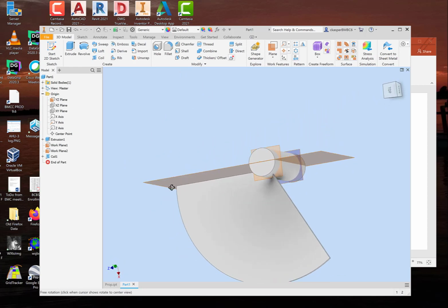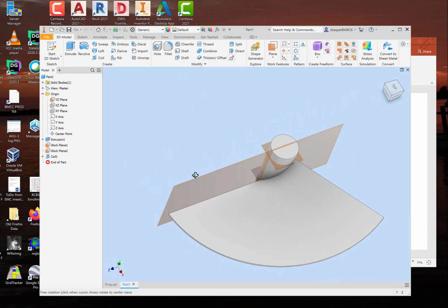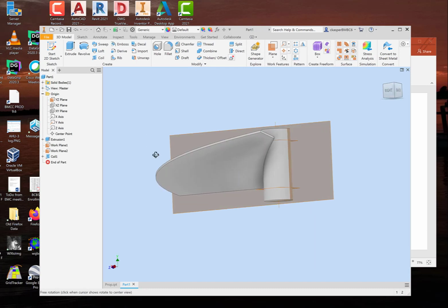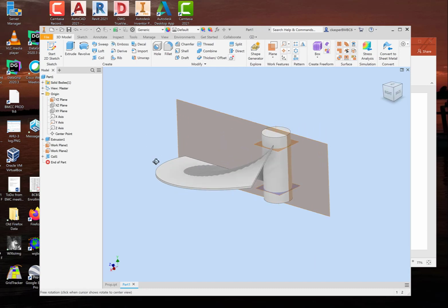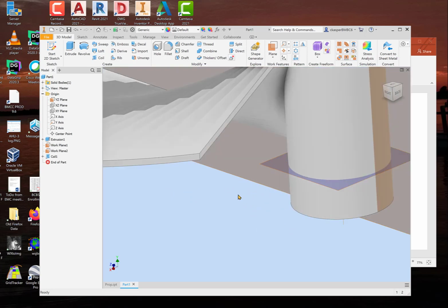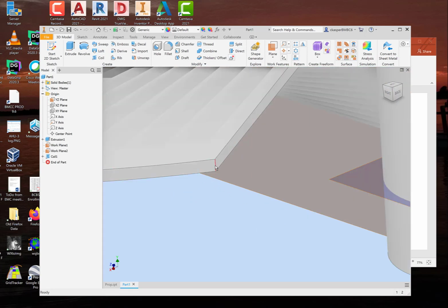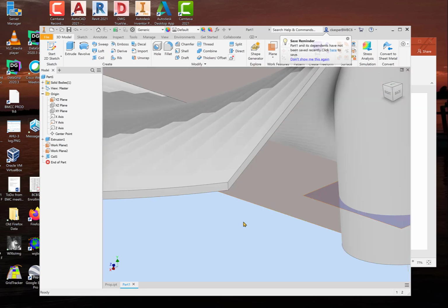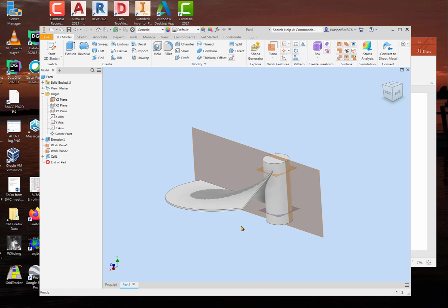Almost looks like a fan blade to a fan. Well, what we need to do is soften up the edges. Otherwise, this one would never survive. And how we do that is, if you zoom in to that little spot right there, we need to push that in and make it what's called a fillet. Okay, so I'm going to zoom back out. And let's hide a few planes because it's kind of hard to see.